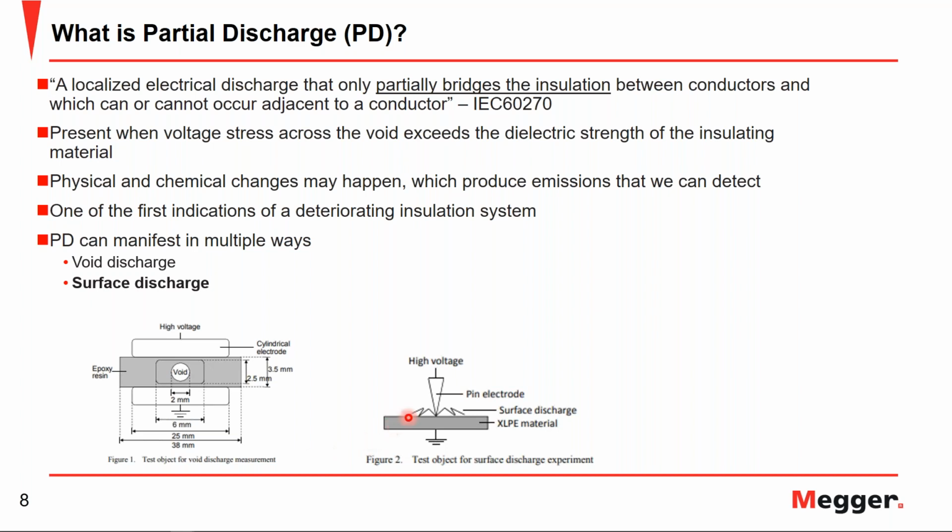And this is where you can actually see the partial discharge taking place, and that could be due to maybe a punctual effect, exceeding bend radius on cable, contaminants. There's several different cases in which that could happen. But you can actually see the discharge is taking place between your high voltage electrode and that XLPE surface there, which again is going to cause that carbon tracking and get worse over time, and could result in a breakdown there.